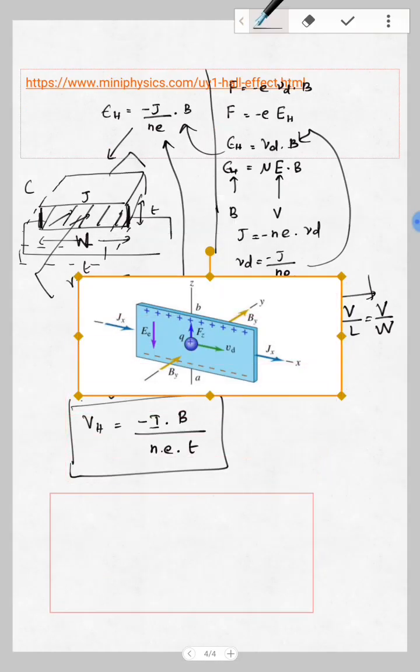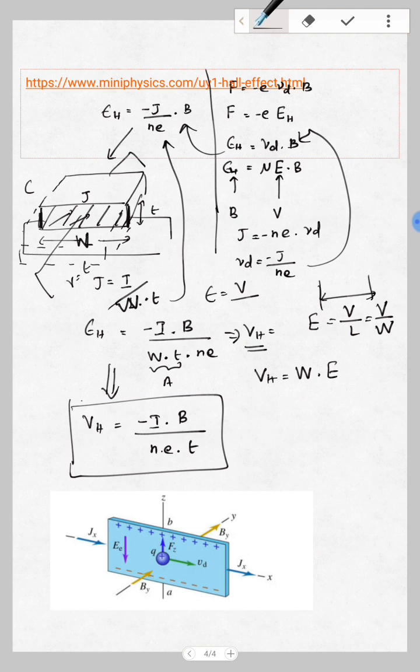If I take this picture, this is holes carrying the velocity Vd, in this direction from left to right, and this is my index finger in the right hand principle. If I take the cross magnetic field, the magnetic field is the middle finger, it is going inside, so the force is going inside.